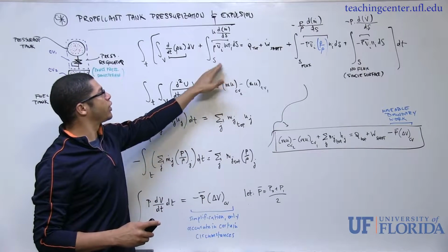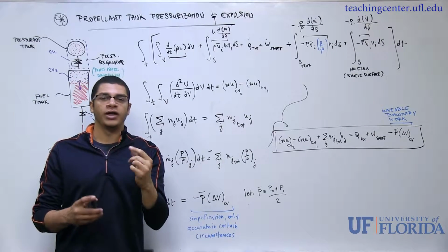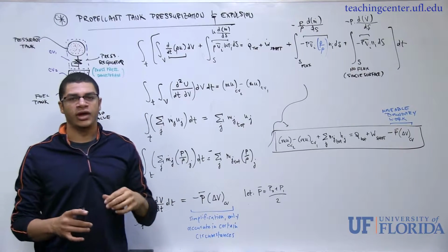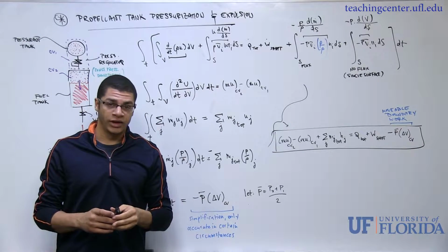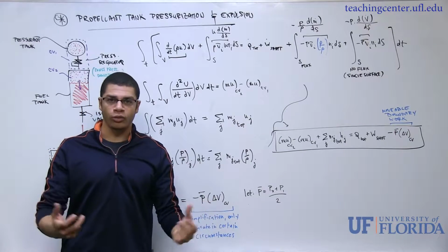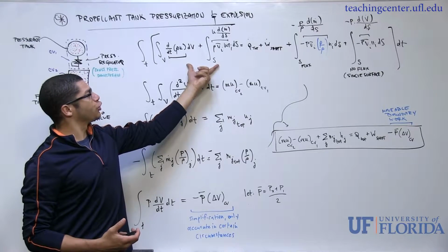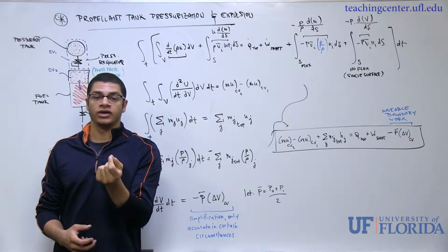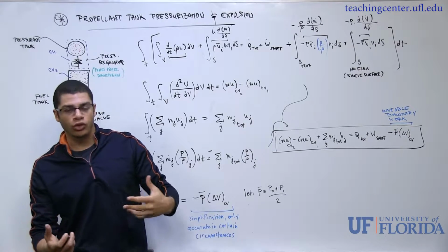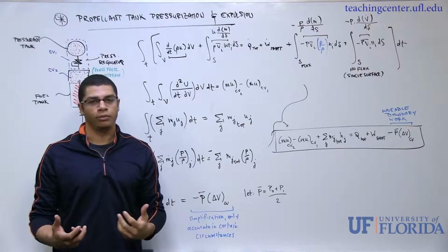And prior to these, in the enthalpy video, we had just a single term that we were able to break into two. There was a time derivative outside of an integral, so we were taking a derivative of a deformable control volume. So we could replace these two terms here with that single time rate change of the total internal energy of our deformable control volume that contains the same particles.